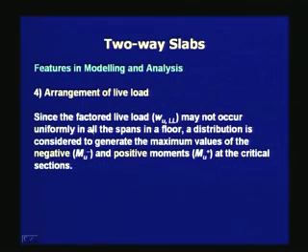The fourth point is the arrangement of live load. Since the factored live load WULL may not occur uniformly in all the spans in a floor, a distribution is considered to generate the maximum values of the negative and positive moments at the critical sections.